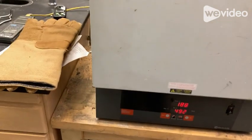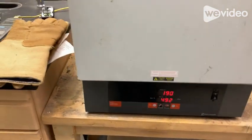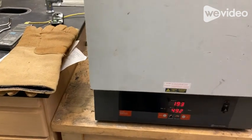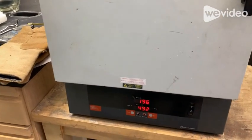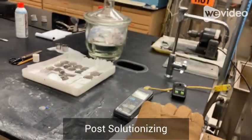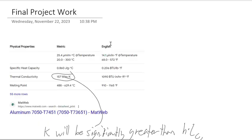And after that, I'm going to go back through the same test I showed you before. I'm going to set this furnace to 135 Celsius overnight after I finish solutionizing here, just to make sure that the temperature is going to be uniform throughout it. And from there, we'll see what differences there are in the heat capacity. You can't tell with the quality of the camera I have, but it looks a little bit different. Looks like it's going to be about 135.7 Celsius.